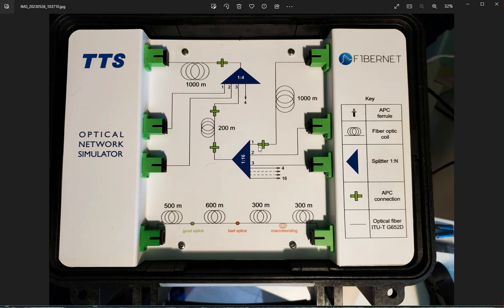Again, the pulse will continue to propagate through the 1000 meter and then terminate at the top right connector here. With the OTDR, the pulse will simply continue to flow as long as there is a fiber path, an optical path for it to flow. And the OTDR trace will be showing that longest path down that link.